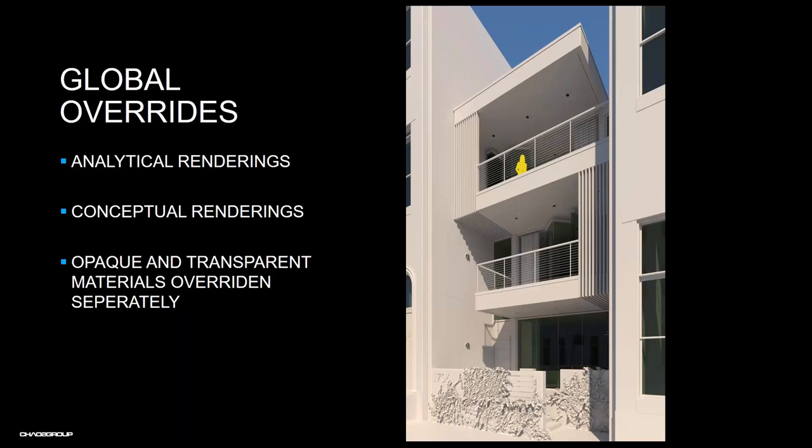For the sun position, we render with the V-Ray sun and sky system, but we grab the transform position from the daylight system in Revit. Everything is based on the idea to keep the data, the metadata, the information of your model itself. So you keep the data in your project. Just for the image, you can override everything.